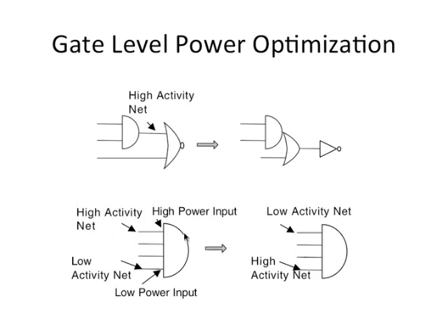You also have, sometimes, gates which might not be symmetric with respect to the capacitance at the inputs. So this is just some gate with multiple inputs, for example, a 4-input NAND gate, and the sizing in this gate is such that the top input has a higher gate capacitance. If that net is a high activity net, you can just switch it. Again, it's a very simple common sense type approach.